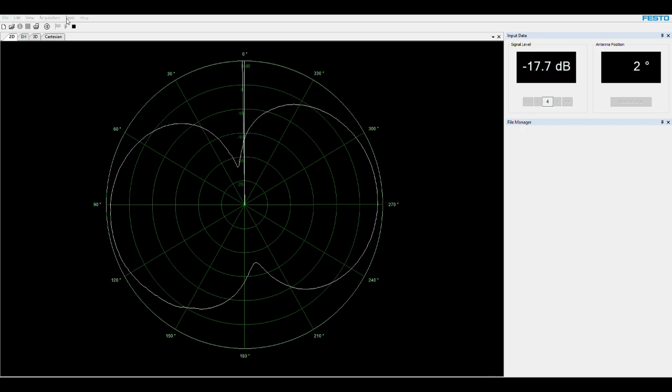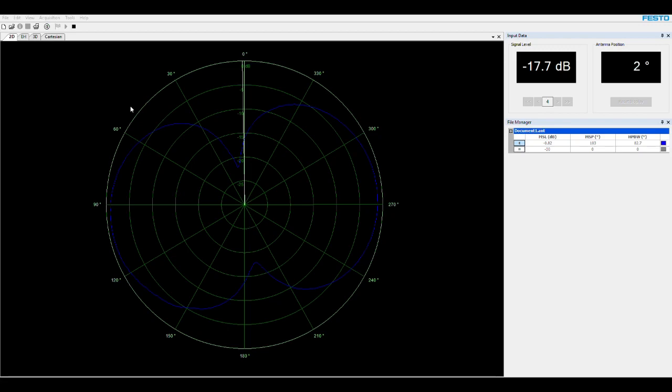Okay, so that's the E-plane pattern for this antenna. So what I can do, I can just save it under E-plane. So it's actually the pattern that we got is reasonable. As you see, the half power beamwidth theoretically should be 78. In this acquisition, we got about 82.7.